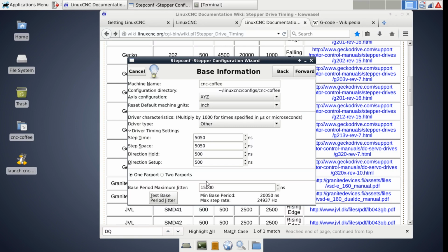Now, these low-level modifications are also why you're not going to use a regular Linux distro for running a CNC machine. So if you already have a computer with Fedora or Ubuntu or Mint or any other Linux distro, you probably aren't going to use that for your CNC machine, because applying those kernel patches is such a royal pain. That is why the LinuxCNC guys came up with the ISO install, because that packages the entirety of LinuxCNC and the modified kernel all as one unit.